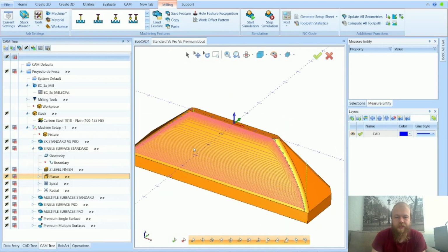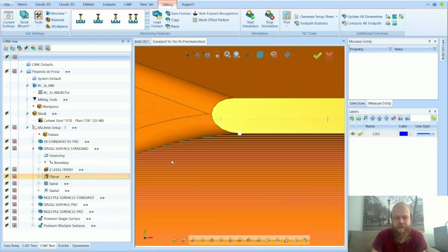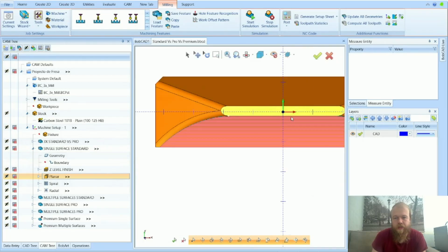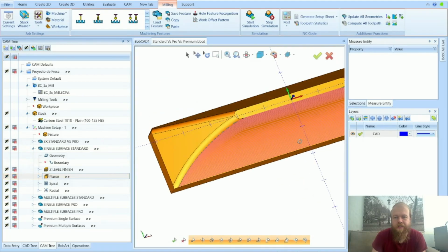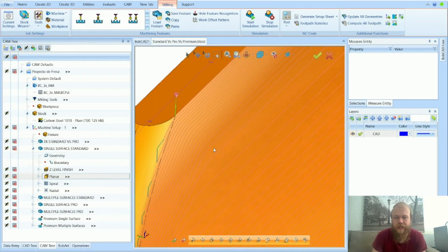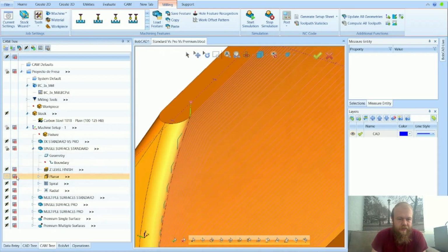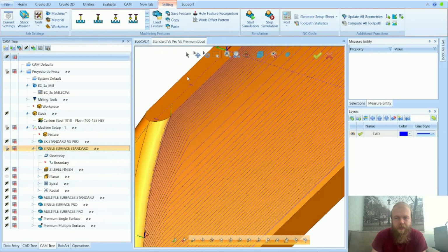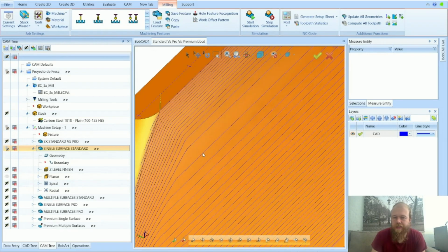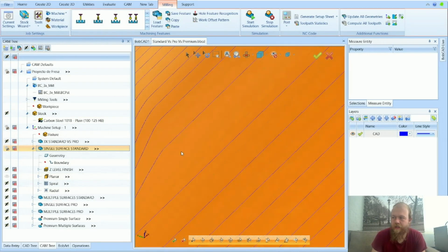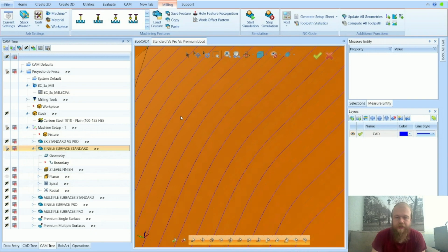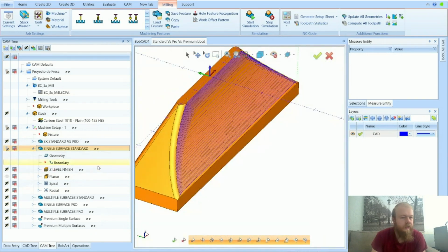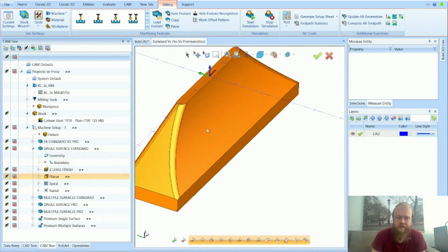But even with the planar toolpath, if we look at it from a top view, it's going back and forth like this. It doesn't follow the curvature of the shape, so you can see the step over is kind of weird right here. Kind of hard to see with this pink toolpath, so let's see. There we go. It's better in blue. You can see the step over like this. Much larger step over than when we get up here. All right. That's again good with the premium toolpath that we're going to get into later.